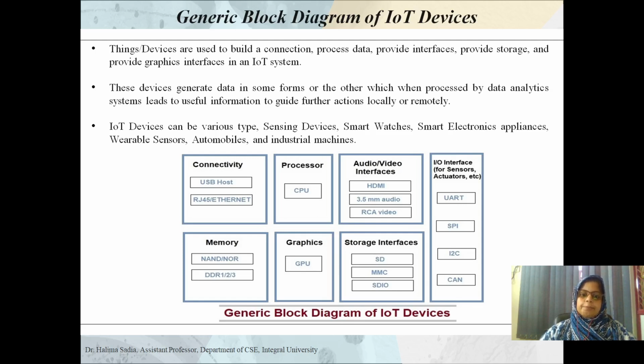It also separates the clock and the data lines along with the select line to choose between the devices that a particular user wishes to talk to. It is a master and slave type protocol that provides a simple and low cost interface between a microcontroller and its peripherals. So, the connectivity will be a master slave kind of connection.